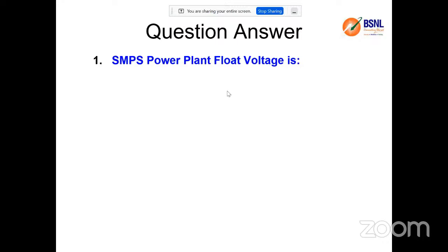So from the participants, can anybody come and say what could be the float voltage we have discussed? 55.2 volts, sir. 55. So that is a charging voltage, madam. Thank you very much. It is a float voltage. It will be 1 volt lesser. It's 54. Thank you very much for your participation. So that's why I said float voltage will be moderate, charge voltage will be the maximum.